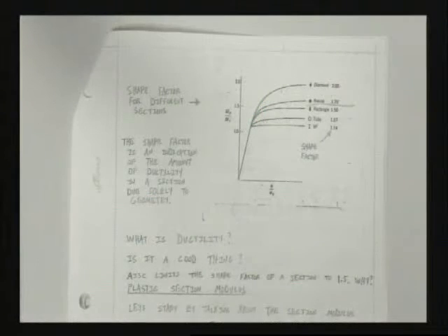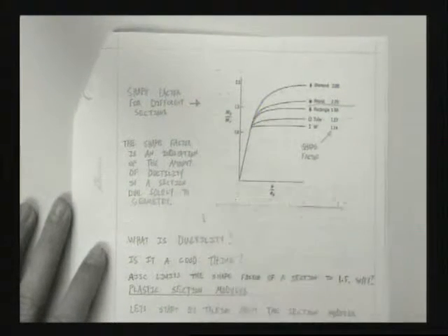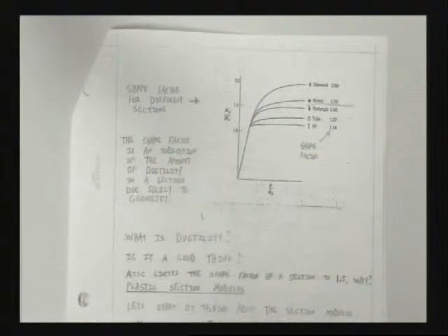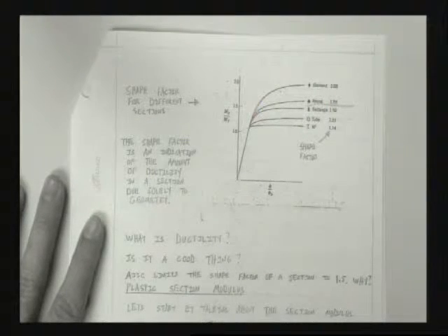Awesome! Now, the cool thing about the shape factor is it actually depends on the cross-section. Again, this is all assuming constant yield stress. We don't have a constant yield stress, so everything goes out the window. But remember, the shape factor is pretty cool because it's just about the cross-section you use. It gives you the ductility. It's a measurement of ductility. Well, that's what ductility is, right? The area underneath the stress-strain curve, the amount of extra you have between first yield and ultimate plastic failure.